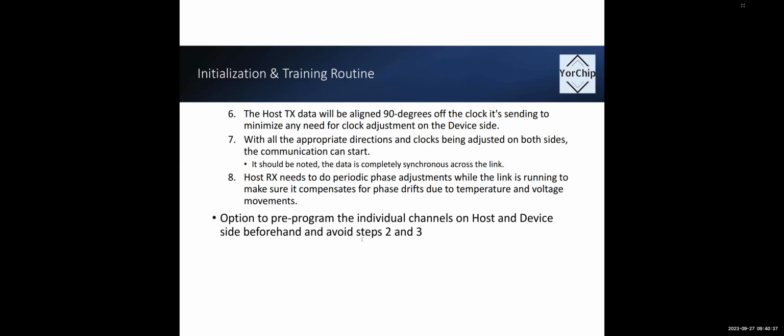The primary benefit, I guess we can argue two things. One of them is that the receive side technically doesn't need to do any phase alignment for receiving the data. Hypothetically, it can use that same clock. Again, there are a lot of delays involved inside it, but hypothetically it can use the same clock to receive or sample the data without doing anything on top of it. Does that make sense?